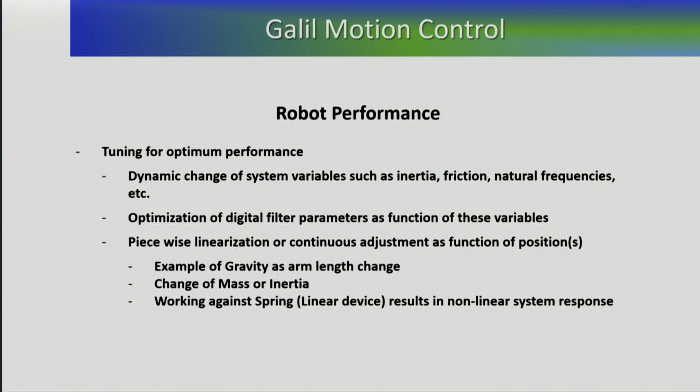As the theta changes, I can apply those changes, and the controller allows you to do that. There are other issues that are involved. We talked about the friction. Friction can change the impact of gravity against not just the inertia, but the gravity changes as the arm extends out. Now the lever arm is a lot larger, and you have to apply for the gravitational offset.